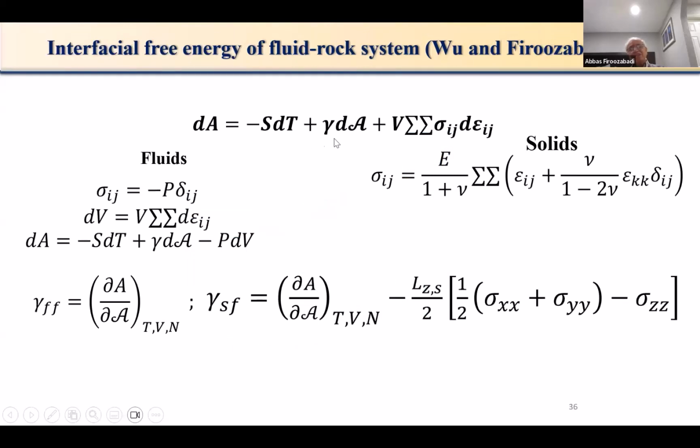So this is the Helmholtz free energy expression for deformable media. If I wanted to have a fluid, this term becomes minus PdV. One complexity in solids compared to fluids is that in the bulk we are not dealing with pressure and volume, which are scalars, but with stress and strain. These are tensors, so it makes the calculation more complicated for the case of deformable solids. So the difference really here is this term. The case of fluids is much simpler.